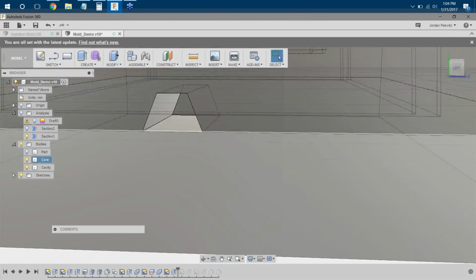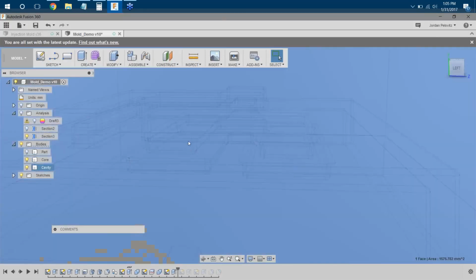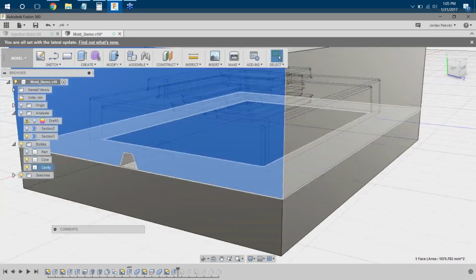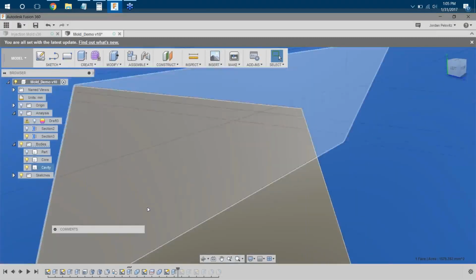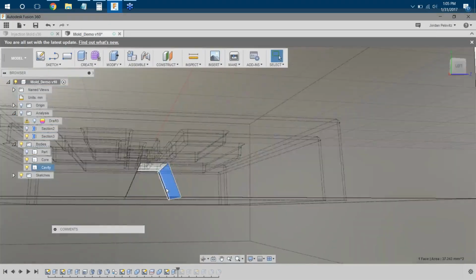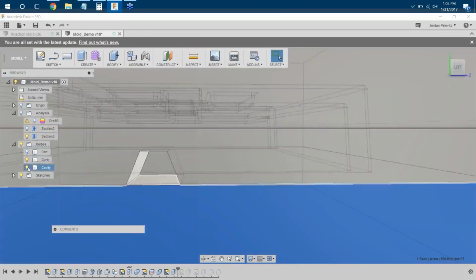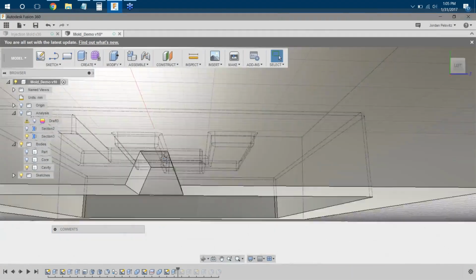In general, you want to have your injection port be on both sides of the mold. The reason for that is if I added an injection port all the way up here, there's no way for me to remove that little sprue once the part comes out of the plastic, because it would be completely embedded. It would be an undercut. So by adding this trapezoid down here, I've allowed it to be removable. Like you can see, if I do this, I still have the sprue. I could still access it.